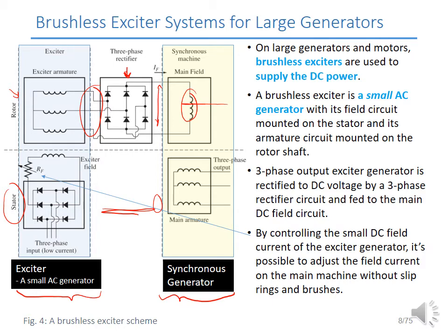And yes, by using this field resistance, the adjustable variable resistor on the stator, if you can see on the left here, we can adjust the magnetic field, and the outcome is that we can then adjust the voltage output of the exciter, and by doing so we can control the output current of the rectifier that feeds into the field circuit of the synchronous generator.